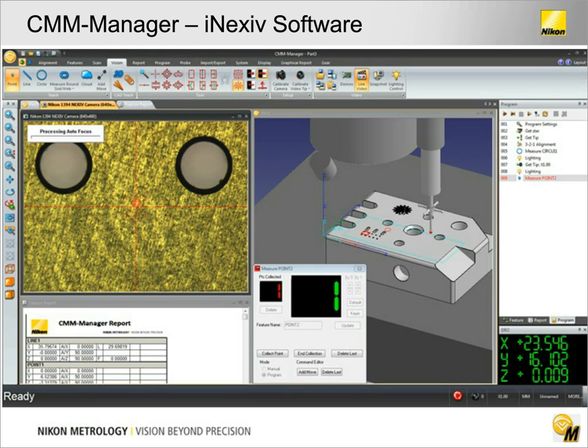Of course, the dialog box is going to have more options if you're looking at measured features that are done automatically. So numbers of points, depth of points, these types of things for tactile probing. On a vision probing, you're going to have all of your options related to the vision tools exposed in these dialogues. And then ultimately, after the operation is added, in the program on the right-hand side, you'll see a representation chronologically of all of the operations within your program.